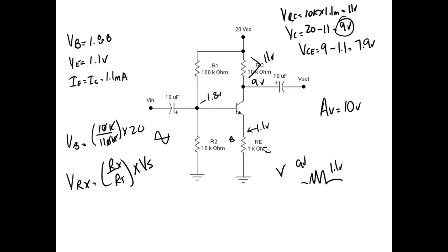So I wouldn't have to measure that 11 volts across RC. I've got 9 volts on one side, I got 20 volts on the other. I've calculated it's supposed to drop 11 volts. And so I got 20 volts on one side, 9 volts on the other. What's it dropping? 11 volts, right? You understand that? So you very seldom see troubleshooters that know what they're doing trying to measure inside a circuit. So we're putting 1 volt peak to peak in.